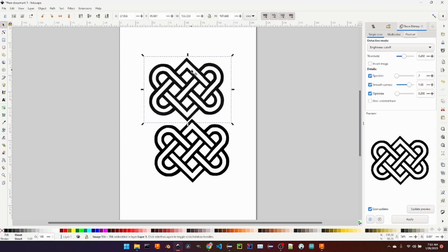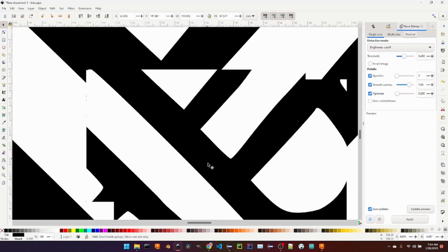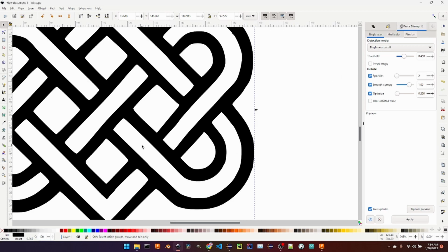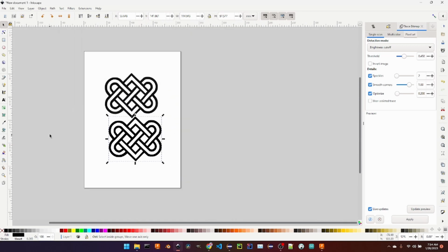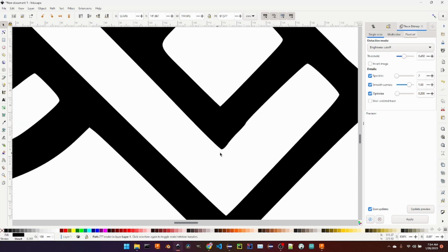Once the image is traced and you like it, you can zoom in, and that's what I highly recommend. Zoom in and especially look at the curve. Sometimes it is weird, like you see here, little weirdness is there, here little weirdness is there. If you're okay with it, and generally you might be, because on a machine this is not clean, but it basically means it's probably 0.001 mm on your machine when you are cutting, which is probably ignorable.